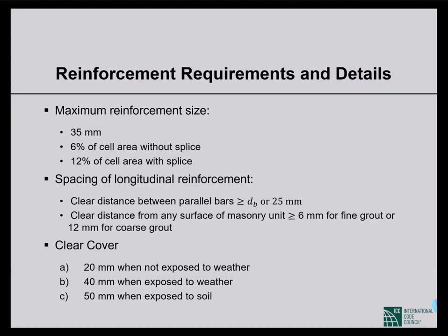In part 8, the weathering conditions are defined, like severe weather conditions. If the weather condition is mild, we can have 20 millimeters of clear cover. If the weather condition is not mild, we have to have 40 millimeters of clear cover. If it is below soil, when the outer surface of masonry is exposed to soil, then the clear cover has to be 50 millimeters. So these are some details.